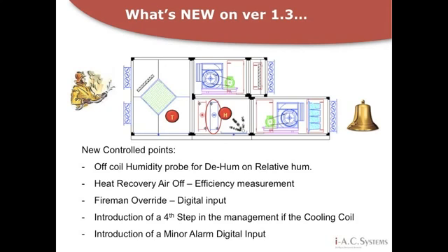Last of all is a handy minor alarm indication which has no impact on the control's effect on the automatic regulation of the air handling unit, but will simply pop up a screen on the display warning of the alarm being activated. This can be handy for remote condenser alarms, for example.